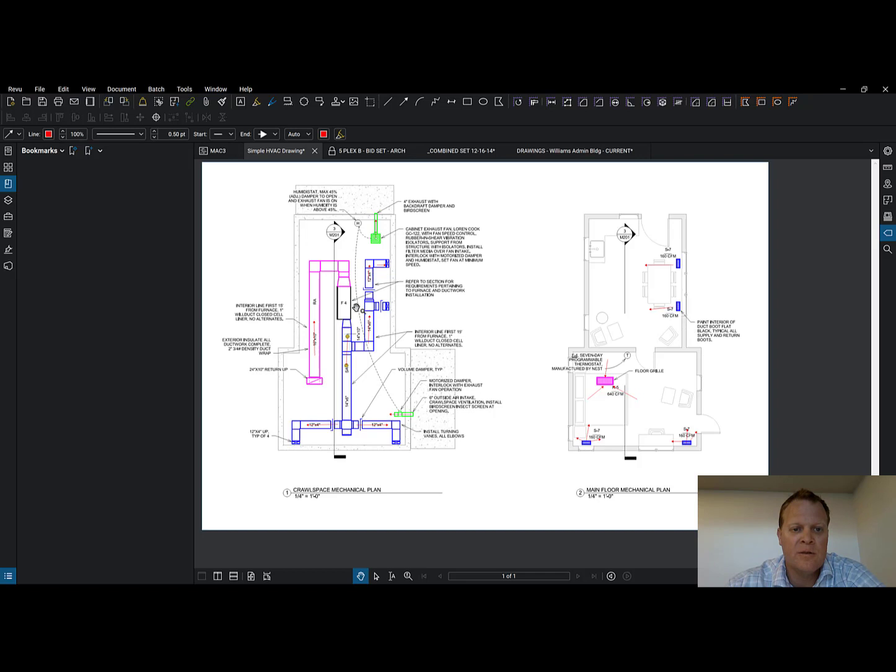Well, I wouldn't. I would rough in the electrical and I would rough in the gas. And we need a condensate line because this is probably got a cooling section in it, even though it's not showing it. And somewhere we've got a condensing unit that we need to coordinate. So there's a bunch of rough activities that we need to figure out: the refrigerant, the natural gas. What if there's a humidity section? It doesn't say there is one, but this is a little addition to a home, so I wouldn't be surprised if this set of drawings just doesn't even talk about that kind of stuff, and the client's like, yes, I want that, of course I want that. Then we got to go figure that out as the general contractor and coordinate it, right?